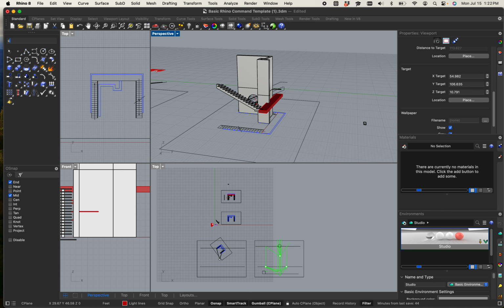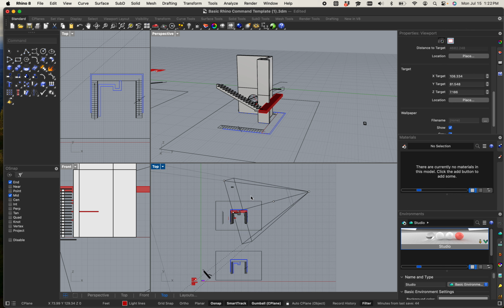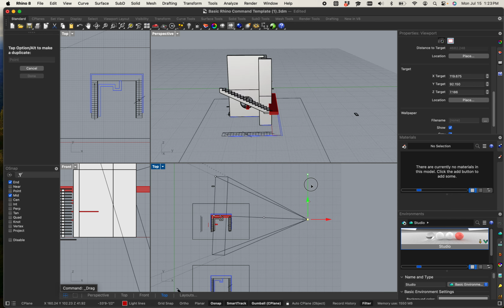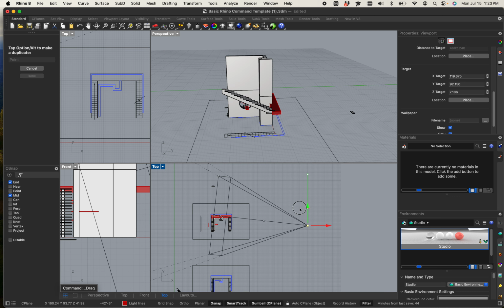Let's go ahead and type in camera, hit enter, and show your camera, and you'll immediately notice that, look, it's that cone of vision that we're always talking about. Well, this is the actual exact same cone of vision that you are always calculating in a 2-dimensional drawing. Here's our stationary point, and you'll notice when I change my stationary point, it changes my perspective view, right? All in real live time.